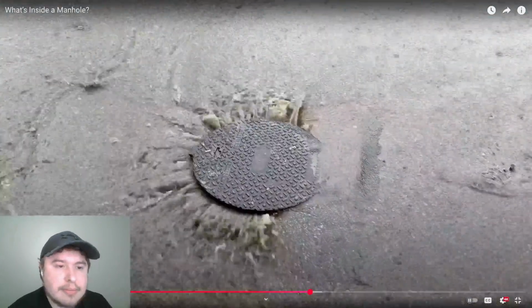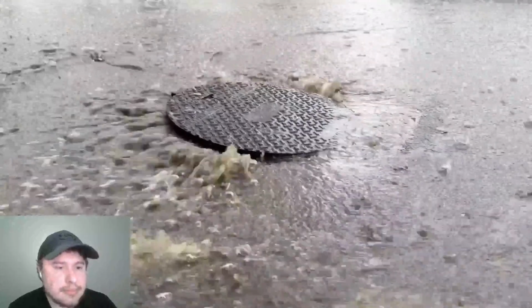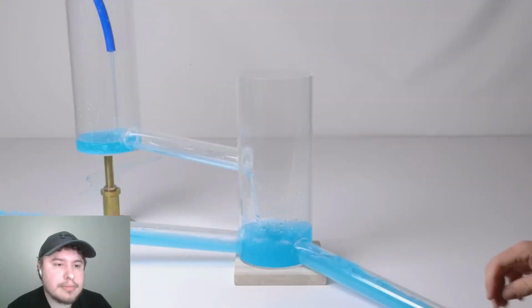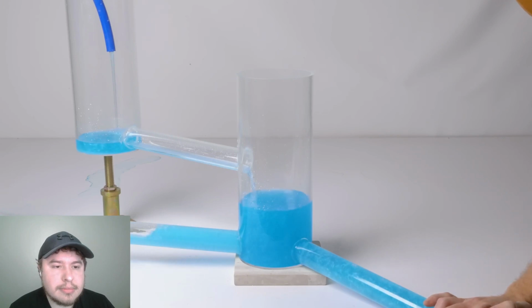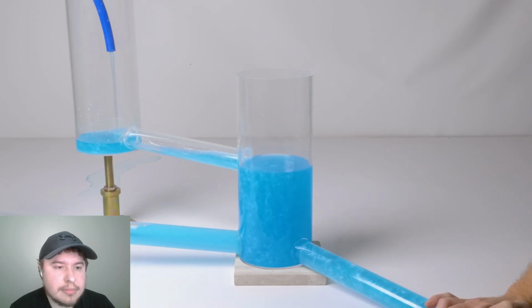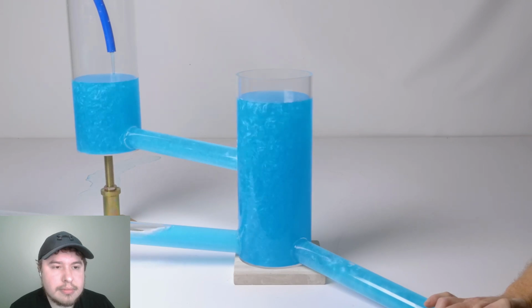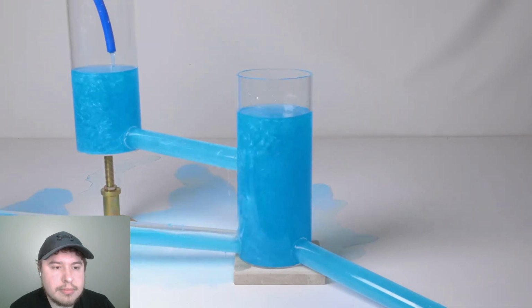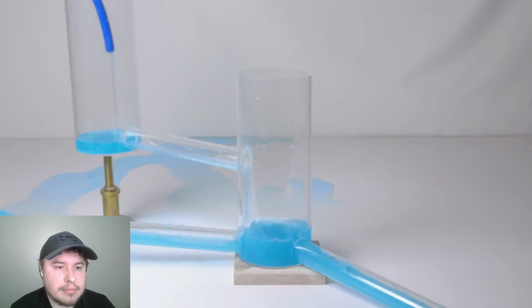But overflows can also happen way upstream of a treatment plant if the pipes are too small. Sometimes that storage available through manholes isn't enough. I can plug up the pipe in my demo to simulate this. If the sewer lines themselves can't handle the flow, you can get wastewater flowing backwards in pipes. And if things get bad enough, you can get releases out of the top of manholes. And of course, this doesn't have to be the result of a storm. Even a blockage or clog in the line can cause wastewater to back up like this.